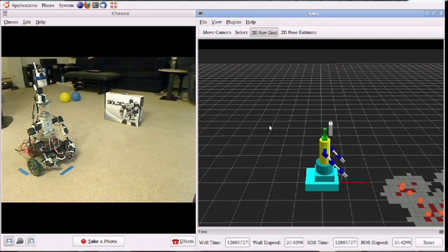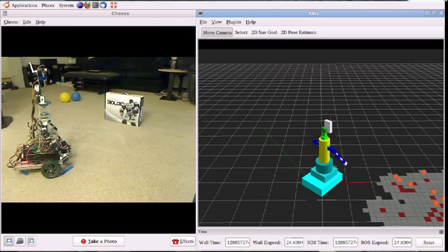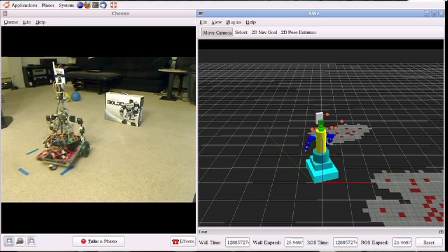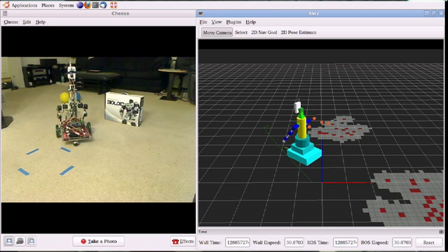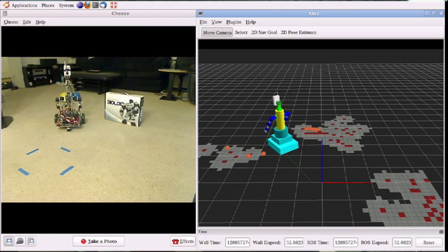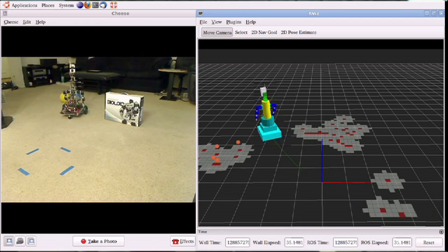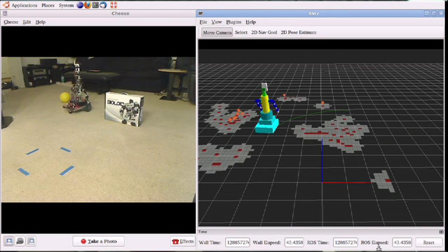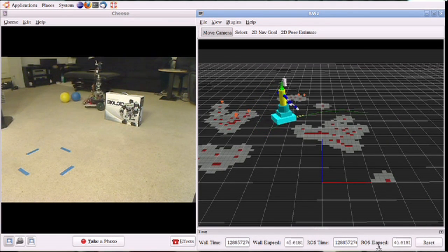And so we have a split screen. On the left is the real robot, and on the right is the RViz view of the robot. I don't know if you can see it, but at the bottom of the robot near the front, there's a little panning IR sensor. As it picks up obstacles, you can see it places those obstacles in the map in RViz. What I'm doing is giving it little discrete commands to go right there with the green arrow.